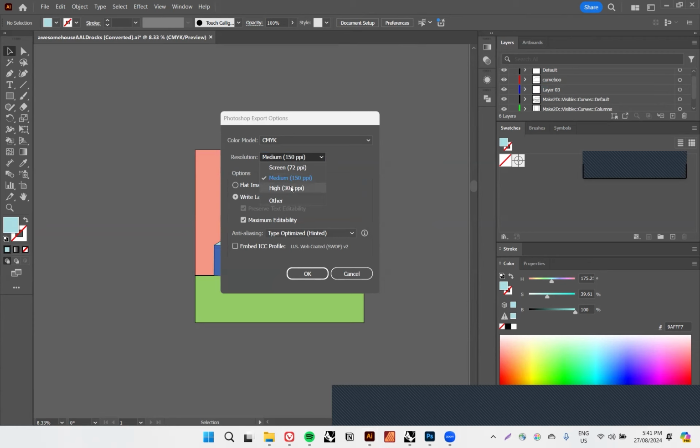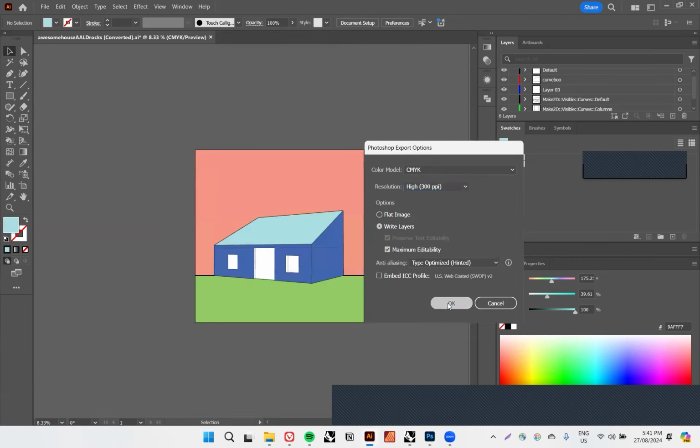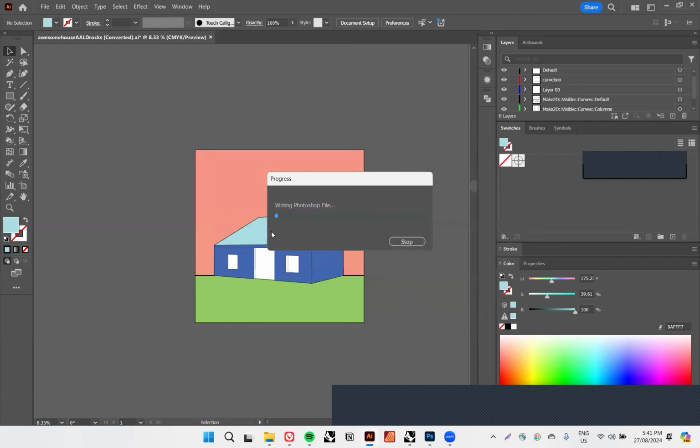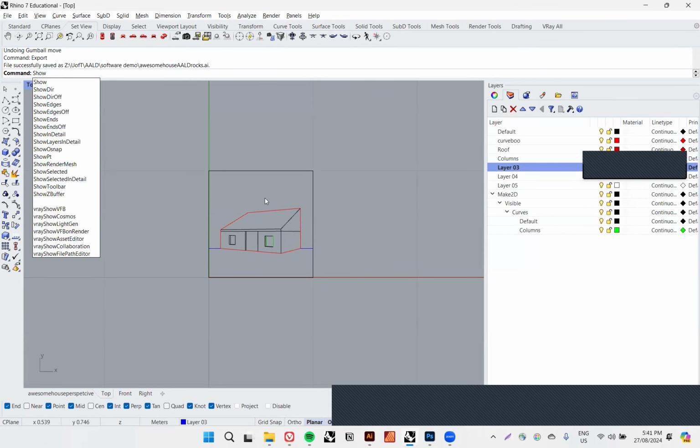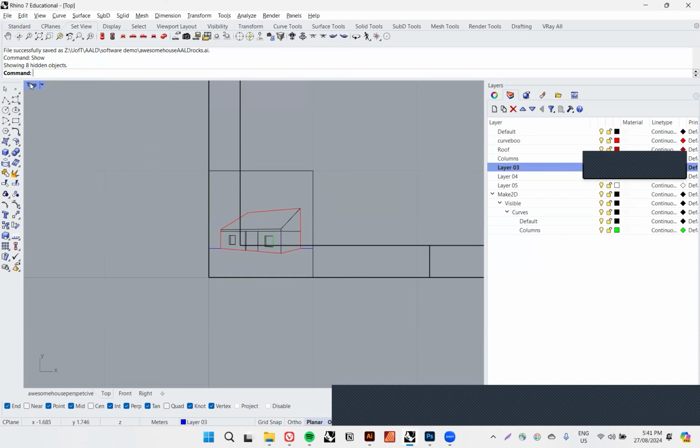It's an image. You want to do most of your drawings, if you're bringing them to Photoshop, at 300 pixels per inch. This allows you to plot them. It's not going to be pixelated. It's good for printing and web. So 300 is the way you want to go. If you want to print it, CMYK is the way to go. If you don't want to print it, if you want to post it on Instagram, RGB is a better color format.